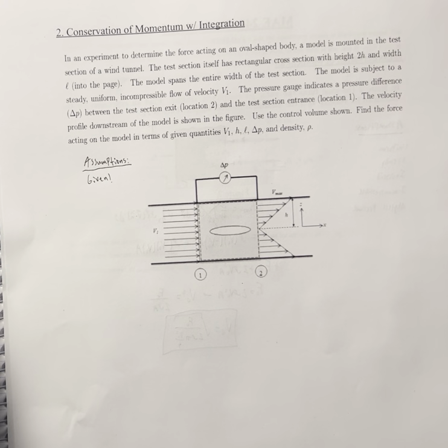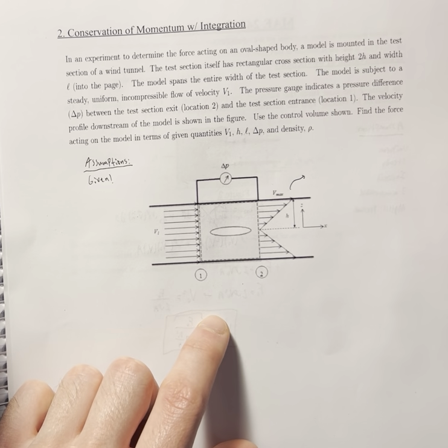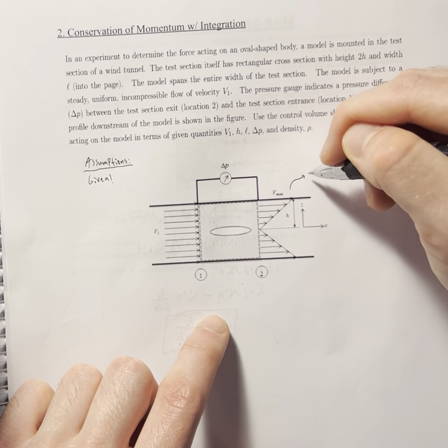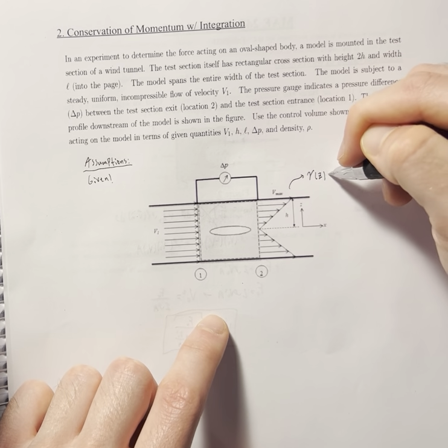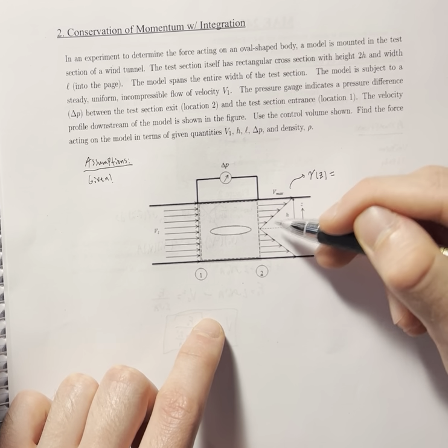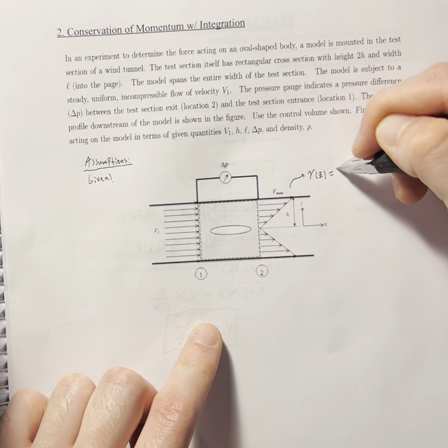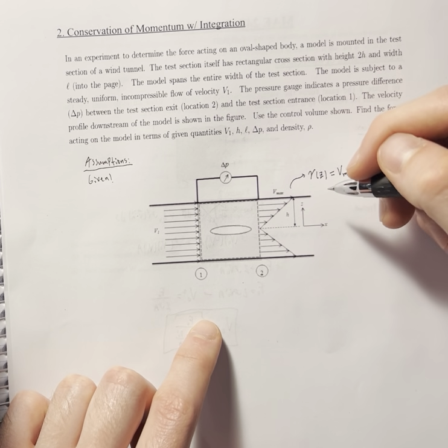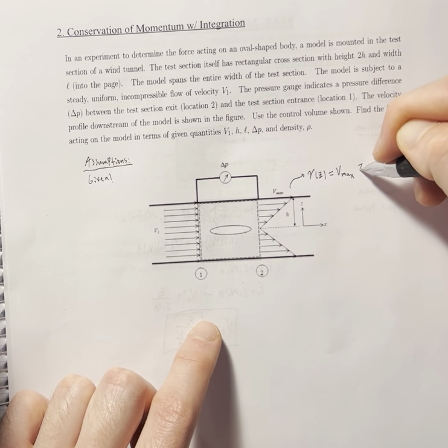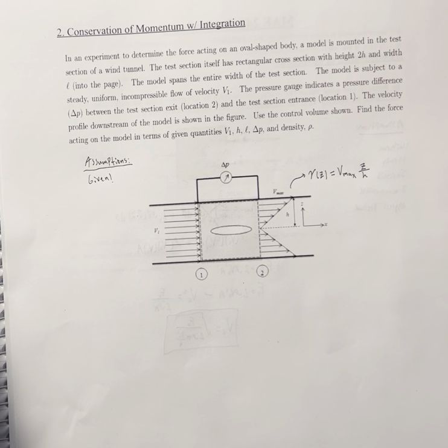All right. And so first off, we need to get this velocity profile. We're going to call this V of h, or V of z, I guess. V of z, and you can see it's just a linear velocity profile where we know the maximum has to be at the edge. So how do you do that? Well, Vmax is going to be our scaling factor. And we want it to be linear with maximum at the edge. So we're going to be stepping with our z. Let's go z over h. Boom. Easy as that.